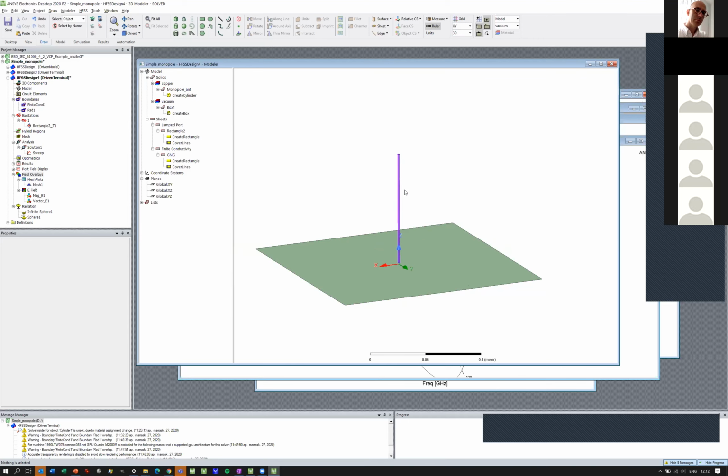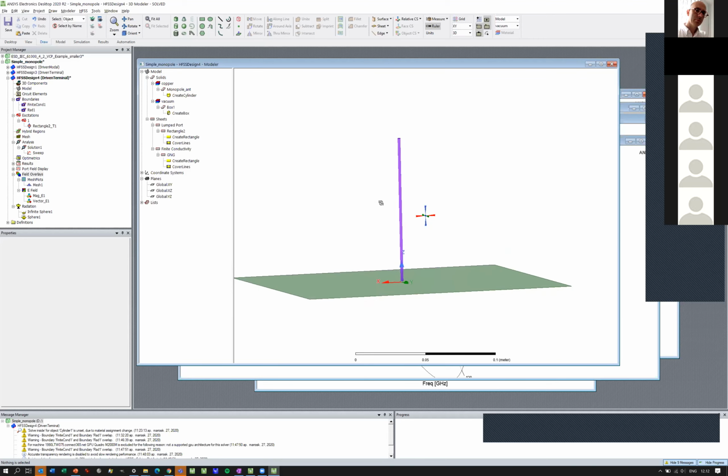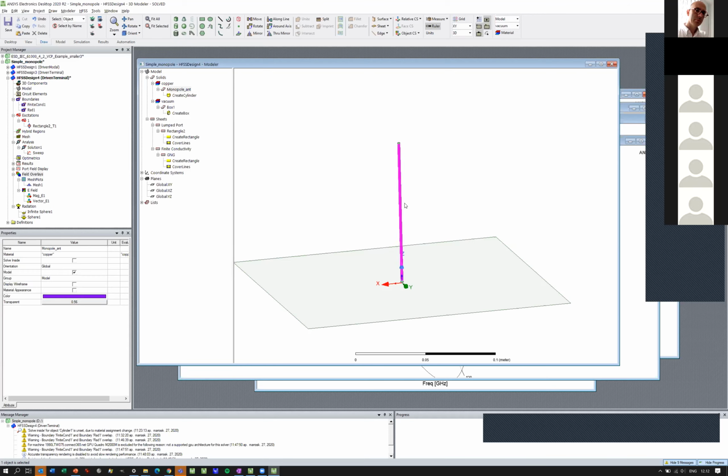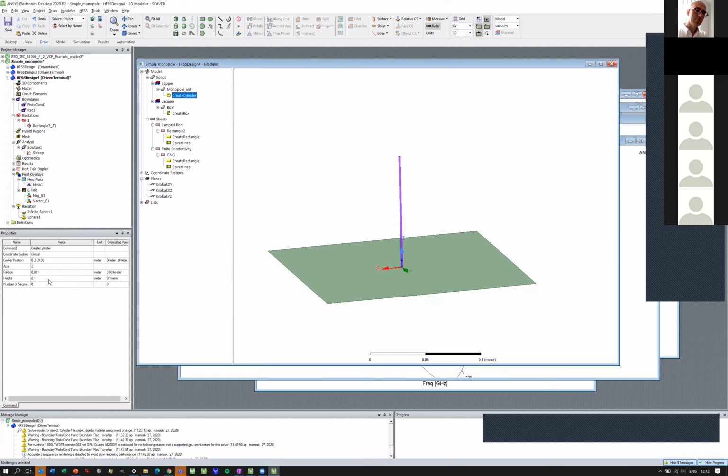The beauty with simulations is the sweep. We can sweep different values. If I want to tune up my antenna, now it was a rigid antenna with a fixed size, but now I can change this height value as a parameter, height.